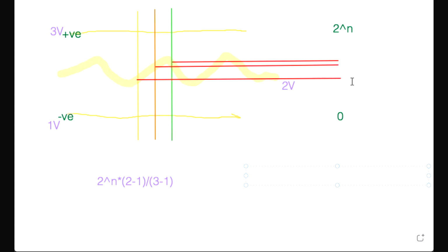You saw that? Yeah. And so that would make life easy. In other words, whenever I get this number out of the A to D converter, all I have to do to find out the resistance is multiply or divide by some constant. Make sense? Yeah, it does. Because it's going to be proportional. Right. So that is all that whole thing was.